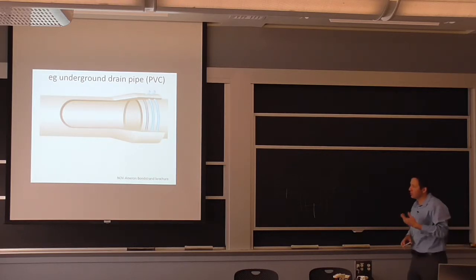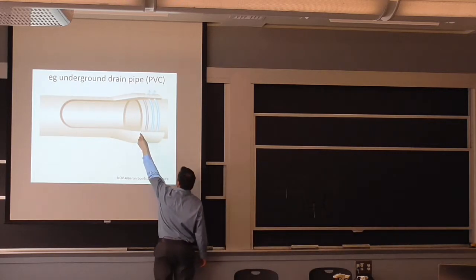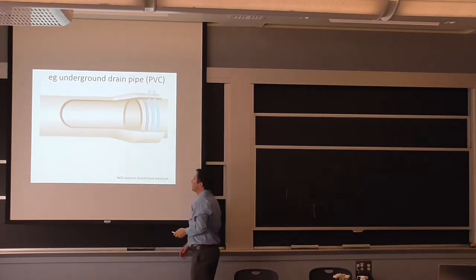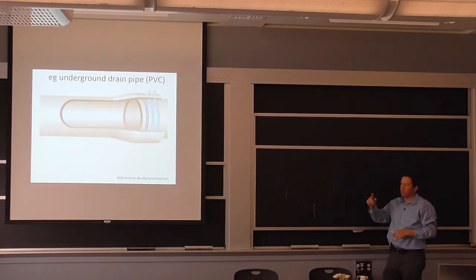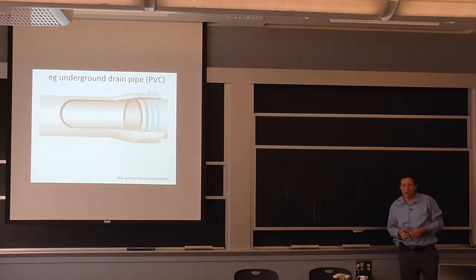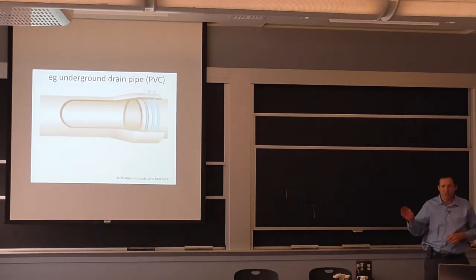And consequently, with this type of design, you rely first of all on the pipe being cut square. So if it does rest here in this funnel or reduced diameter zone, then it's going to contact all around and not at one spot. If it's contacting at one spot, then you can anticipate you're going to have a crack and leakage over time. So it's not the most bulletproof system, and it's only used for normal drainage as opposed to very harsh chemicals or petroleum products.